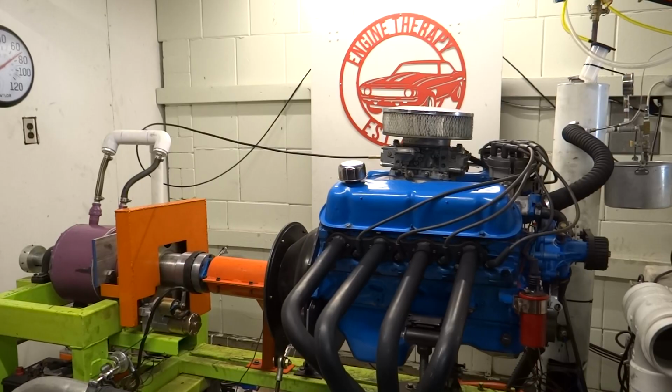So that's the standard I'm going to use, and to my surprise, when I read through this, it didn't say anything about humidity, which I'm curious about. I guess there are other standards out there that do account for humidity, and I think the ISO 1585 may account for humidity, but I don't have that information for sure. For right now, I'm going to use the J1349, which for whatever reason doesn't account for humidity, but it does correct for temperature and atmospheric pressure. I think it'll do a pretty good job of doing the corrections that I want to do.